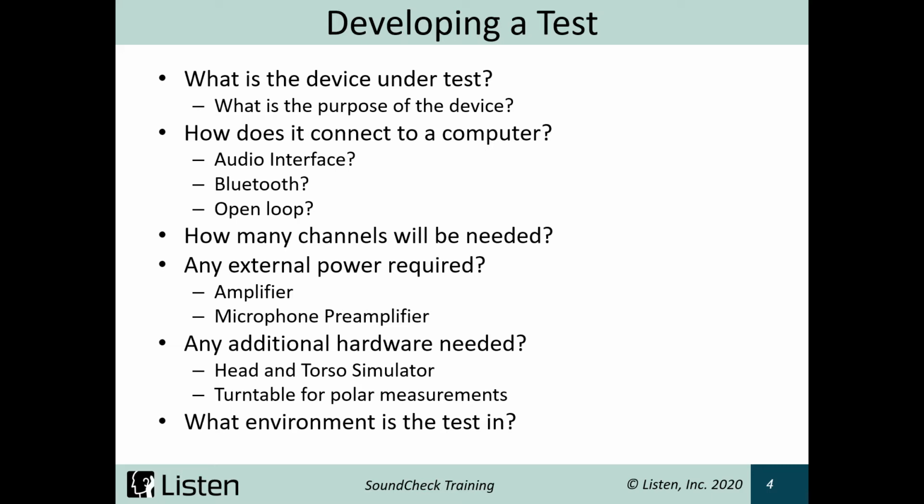If you're going to be reusing the same station for different types of testing, before you start buying hardware and thinking about how you develop one test, it might be good to think about what the minimum for all devices on that test station would be. If one test needs 4 inputs, but most only need 2, you might be better off buying one 4-input device and utilizing that for every test, instead of having to switch around between the testing.